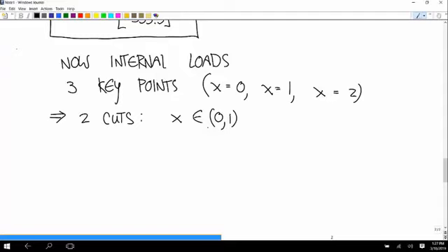So when we do our cuts, the piece that we're analyzing always goes all the way from the solid left endpoint of the beam to a right endpoint that's at some value x. But when you think about what that x stands for, it stands for a range of values that are both exclusive. They're not solid. That's because when we do our cut, x always represents the right endpoint.